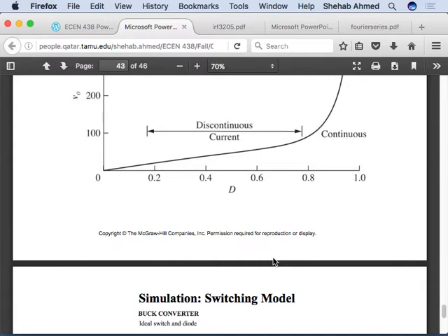These devices are switching on and off, basically changing the load. Right? So they are fed by a power supply, and the load is changing at 3 gigahertz. What does that mean? It means that if I'm going to feed this memory chip or this processor, I need to make sure that my power supply, the step down converter or the step up converter, actually it's a step down converter in most cases, has a good transient response, because typically your processors now are like 1.8 or 1.3 volt, right?